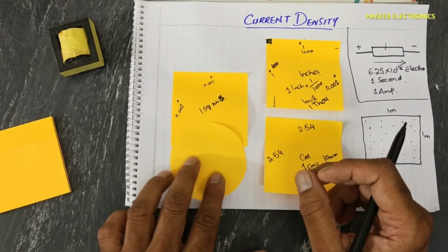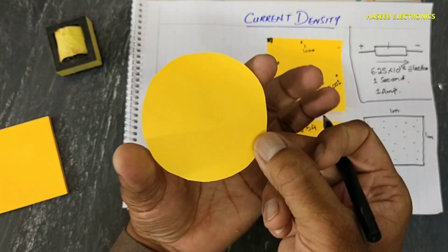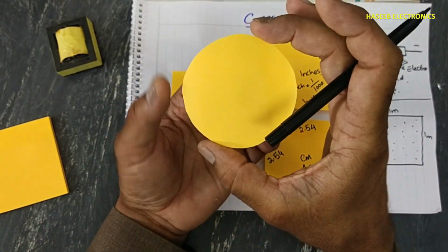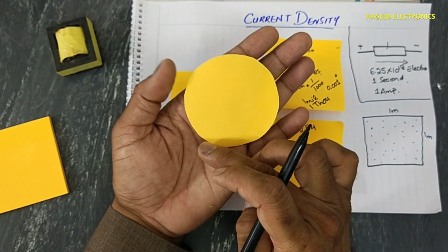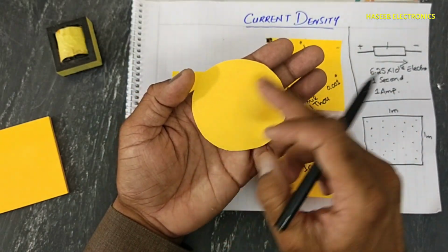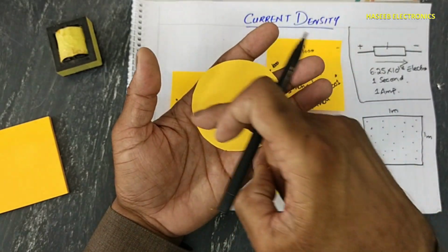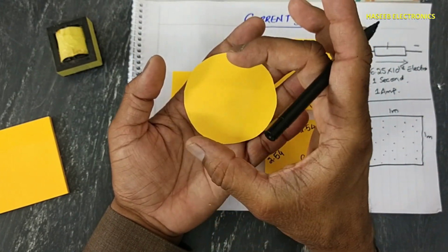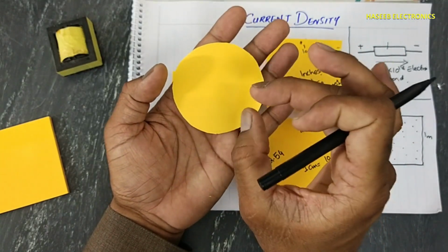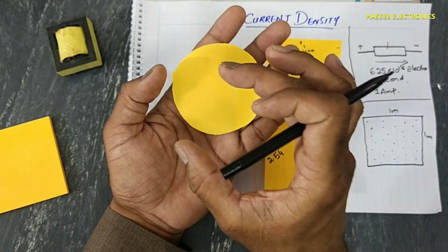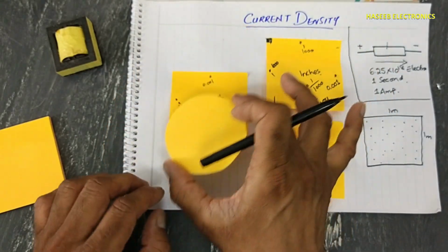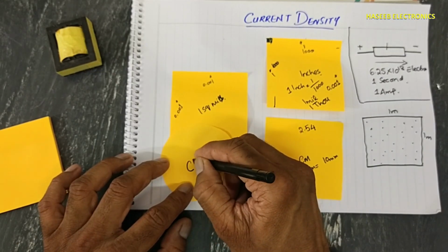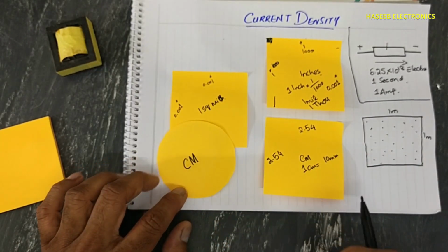When we say AWG wire chart for winding, that shows data in circular mils. If this wire has an outer diameter from here to here of 1 thou, 1 mil, in any direction, because the wire is round, if its outer diameter is 0.001, that means it is 1 circular mil, because it is in circular shape. CM, circular mil.